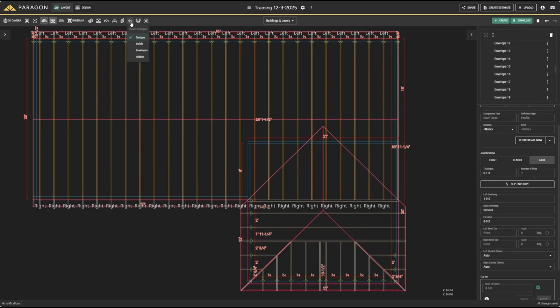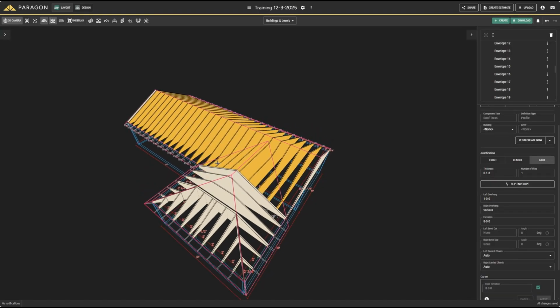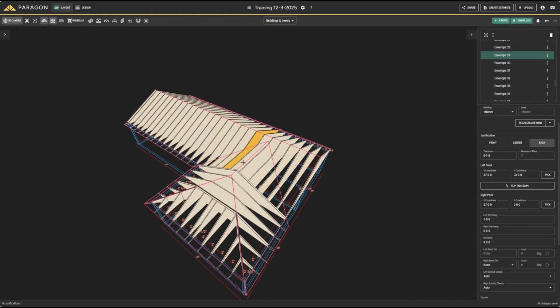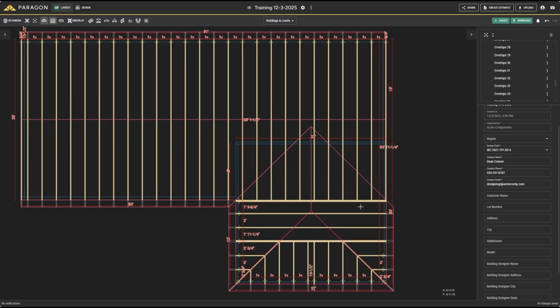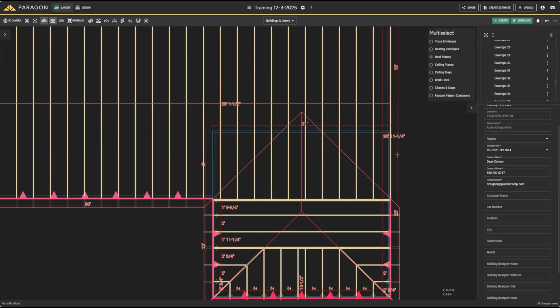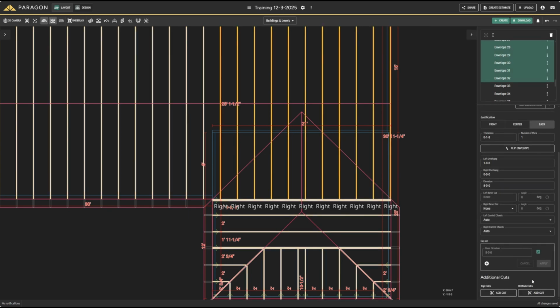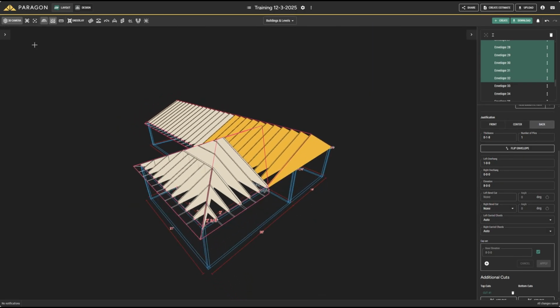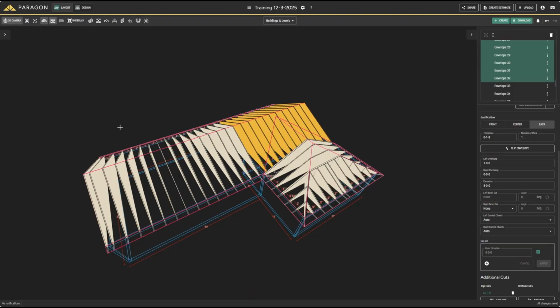Let's turn on our solid truss view and review in 3D. We can see that these trusses here have picked up the garage planes. Let's address this, assuming there will be overframing in the field. Again, we can hold the Control key. We'll select all of these trusses and then add a top cut from the properties. Select the front roof plane. Let's take a look in 3D view. We have not yet added a vault. We will do that later after we initially design these components.